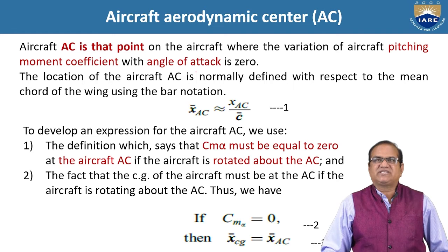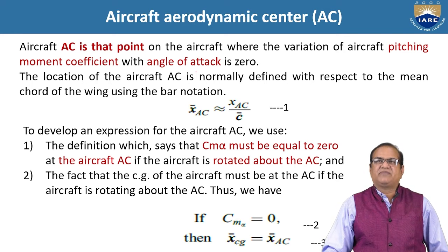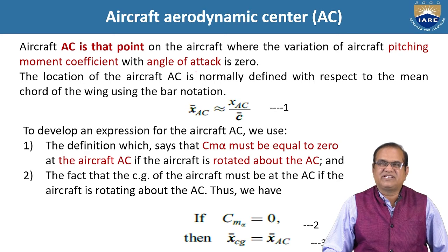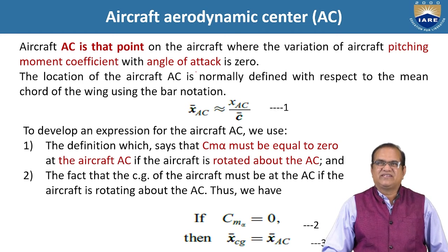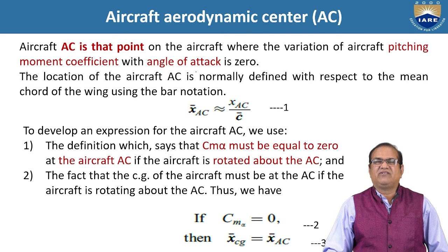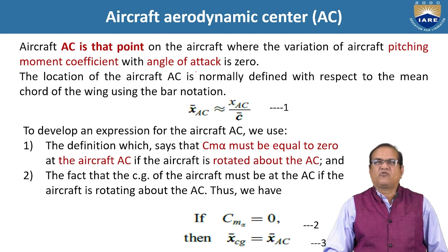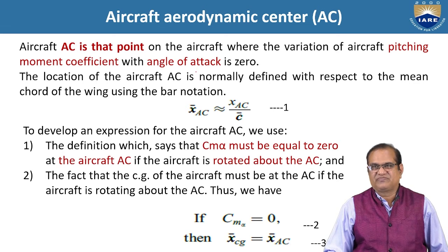Now I am going to discuss the aircraft aerodynamic center. It is a very, very important parameter for studying aircraft stability and control. The aircraft aerodynamic center is that point on the aircraft where the variation of aircraft pitching moment coefficient with angle of attack is 0.